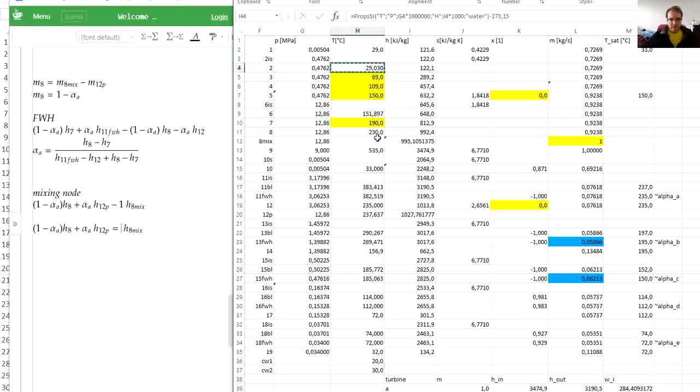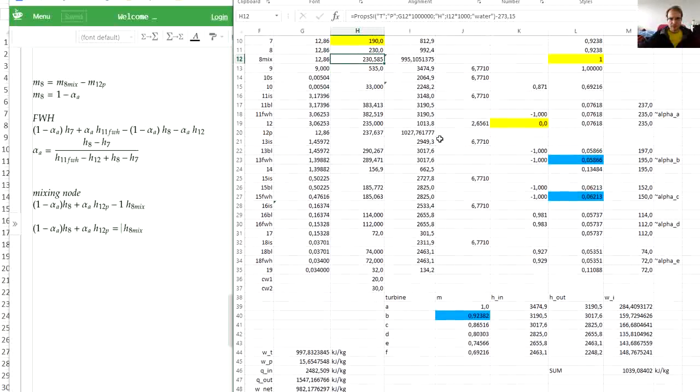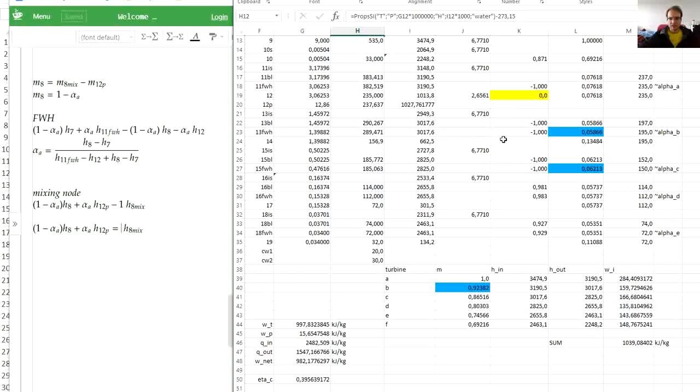Then we can also get temperature, where we can see that by mixing, our temperature at boiler inlet increased by roughly ½ degree C. So now we need to get to our other feedwater heaters, B and C.